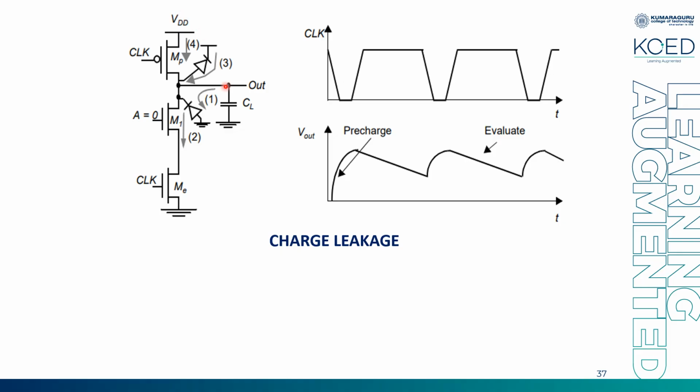So if it is 5 volt here, this capacitance will be charged to 5 volt. Now, if there are unnecessary diodes, reverse bias diodes, or some other parasitic circuits at this place, they will consume some power. Because of these unnecessary circuits being formed over here, your charge will get leaked via those reverse bias diodes. A part of this 5 volt will leak across these reverse bias diodes.